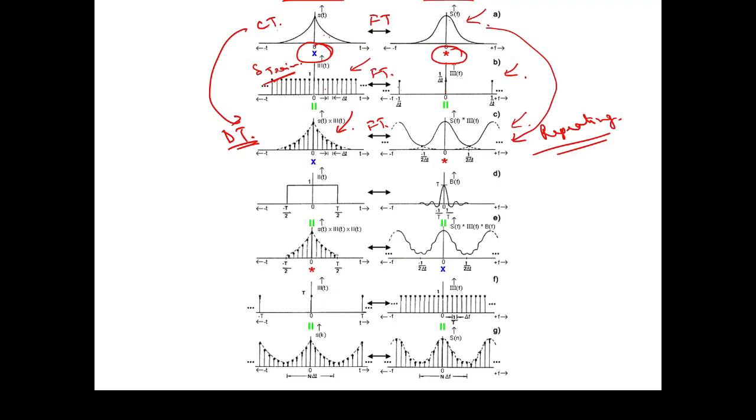If we perform convolution in the frequency domain, you get multiplication in the time domain. So here in the time domain we have done the multiplication, and due to the convolution factor, this frequency component is repeating itself after every 2 pi. Okay. Now since it is repeating itself, we have to take the continuous time signal which is band limited.